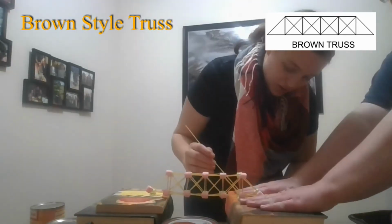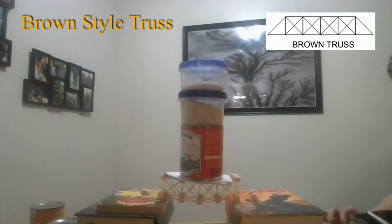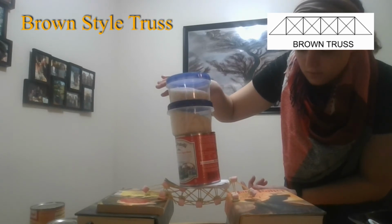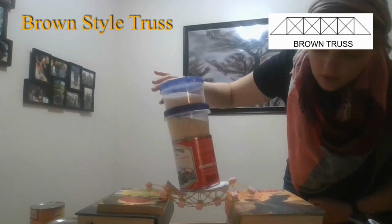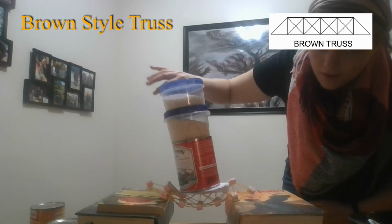Okay, you guys can probably already see what's happening. My marshmallows are a lot softer than the spaghetti noodles, and so my bridge is starting to fail at the joints, and that's why you see this bending, sort of melting motion. And what you can't see from this angle is that my bridge is a rectangular shape if you look at it head on, if you look through the truss, and that shape was beginning to twist out of its rectangle and flatten down to the side.